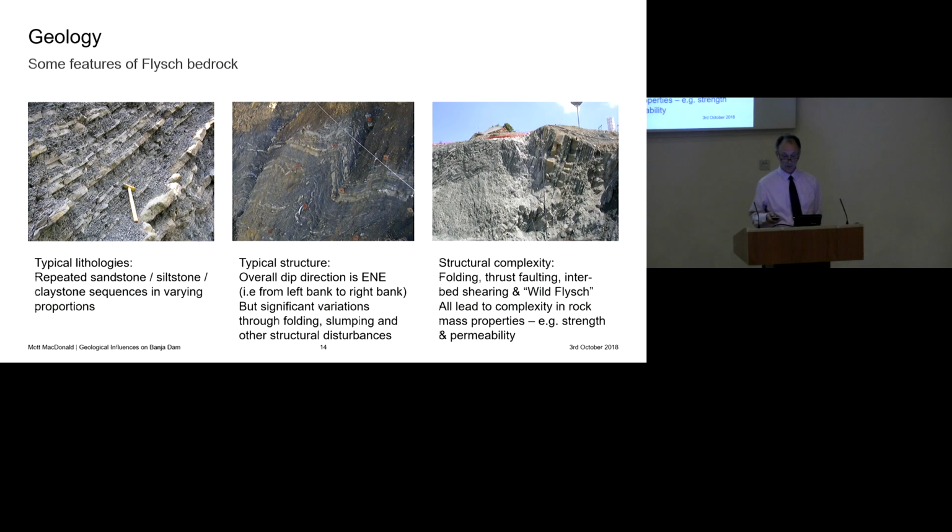And you may be able to see in that photograph that there are beds in various orientations, but I'll help you out a little bit. You can see that towards the left of that photo, you've got largely mudstone beds, which seem more contorted than the slightly more resistant sandstone and siltstone beds, which is what you might expect. But you can also see that the sandstone and siltstone beds on the right are not repeated on the left, and so there's obviously some kind of structural dislocation there as well. So it's really quite a complicated picture.